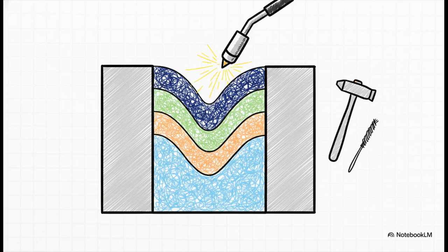Furthermore, the standard dictates some highly stringent rules for the actual welding process. For instance, with circumferential and vertical joints made of material thicker than 40 millimeters, that's about 1.5 inches, you cannot just lay down one massive weld. No way. API 650 enforces strict multi-pass welding requirements. To mitigate the risk of catastrophic underbead cracking, welders absolutely must make multiple passes and completely remove all slag before the next layer is deposited.